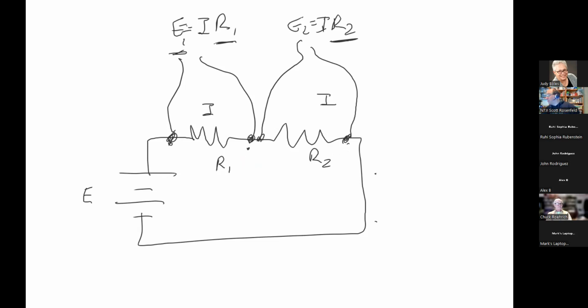They could be. But is there a difference in what the current is going to be when it flows past both of those? No. If they're the same or different, whatever the end result is, the same current has to go through both of them. It can't branch off somewhere and go somewhere else. There's nowhere else for it to go. But the value of the voltage potentially will change.